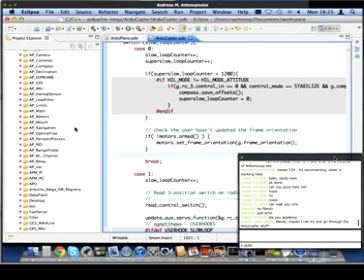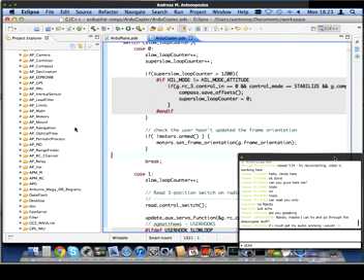You mentioned a while back that it is possible to compile a software copy so that you can run it without having a hardware box, which is good for development. Correct. I do all of my development in software-in-the-loop mode because that way I can simulate the APM. It's actually quite easy. From the command line, if you change directory to ArduCopter, instead of typing make APM2 to make the APM2 version, you type make SITL, and you will be able to compile an executable version.